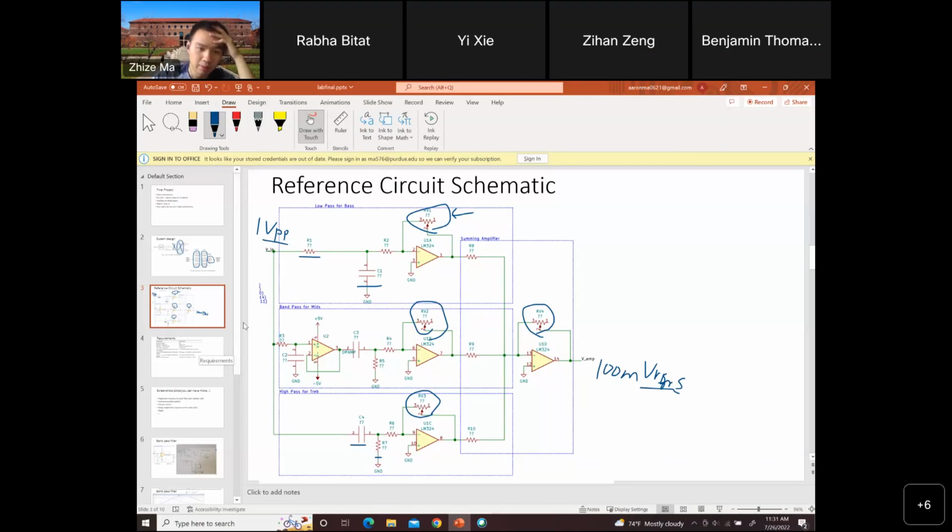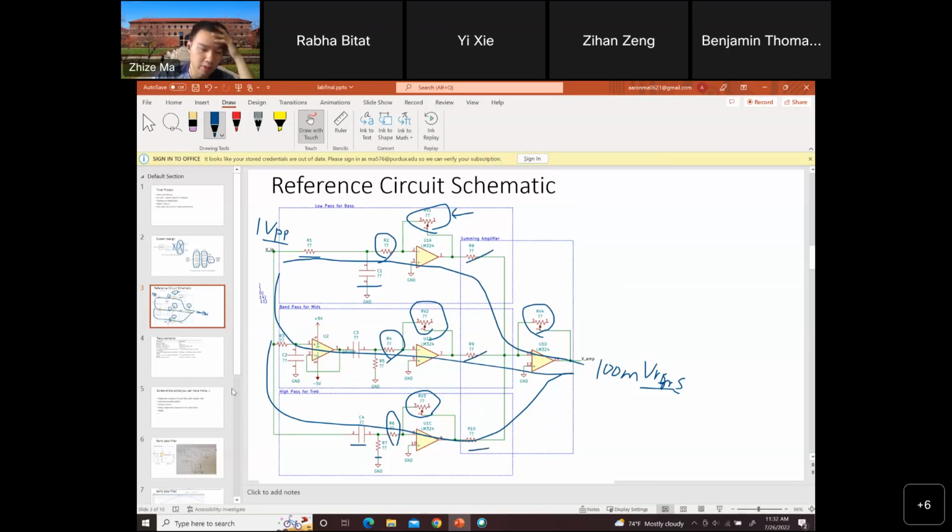Basically the music will pass through the circuit in these three ways in different frequency ranges, which means the gain of each path will be the same. Which means you can use the same value for R4, R6, and R2. And also R8, R9, and R10 can have the same value, since the gain will be the same.